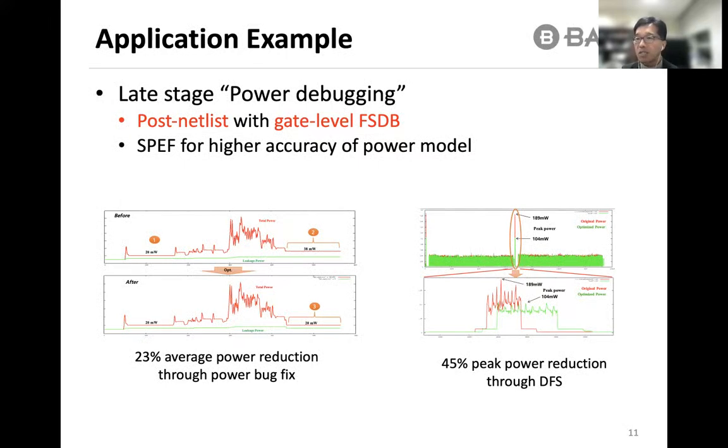It turns out that for this design, some memory blocks were not gated in period 2, even though the GPU function is correct. This could be named a power bug. Such a bug was removed in the updated RTL, as confirmed in the new waveform shown below, which also indicates 23% average power reduction. If only average power is checked, as most solutions in the market do, this power bug will go unnoticed.